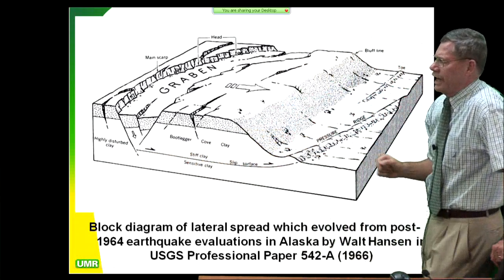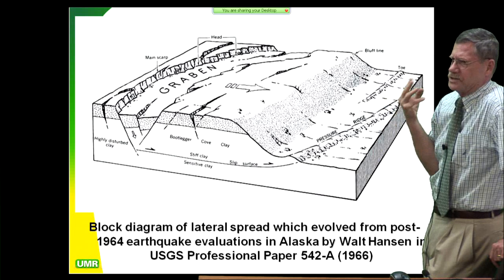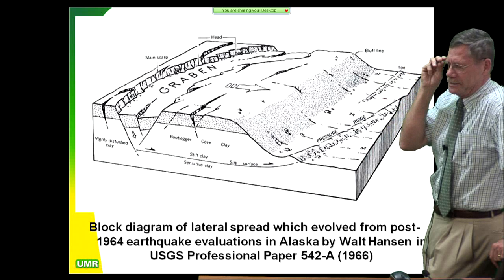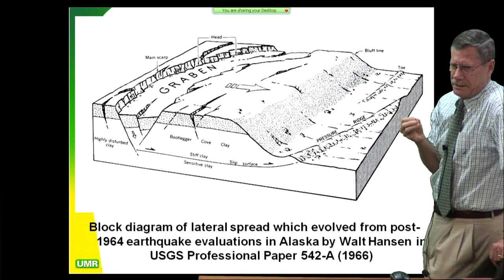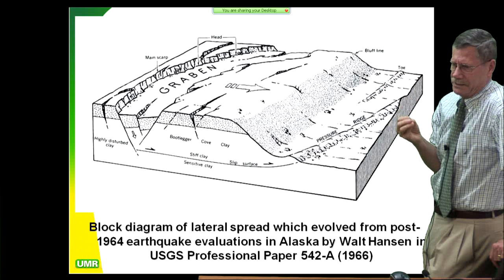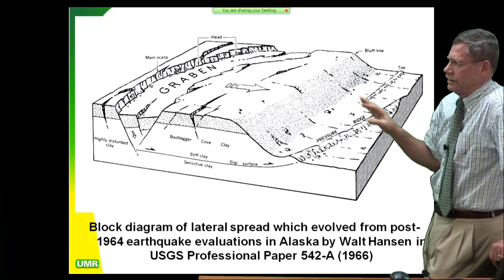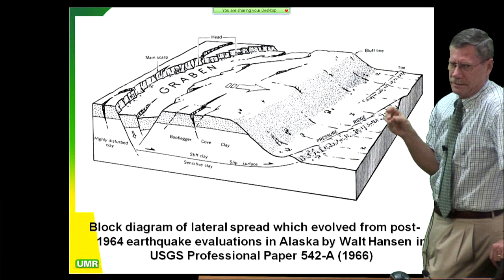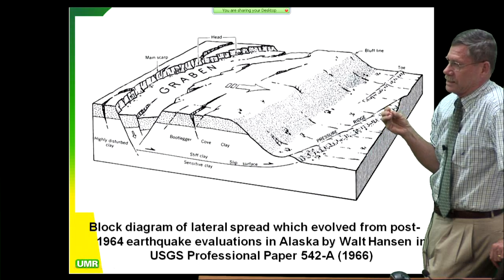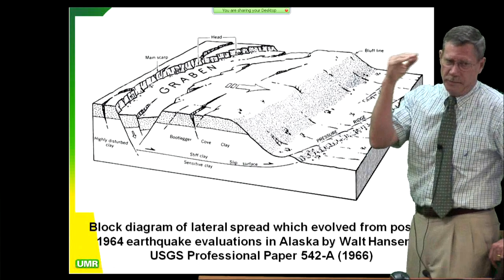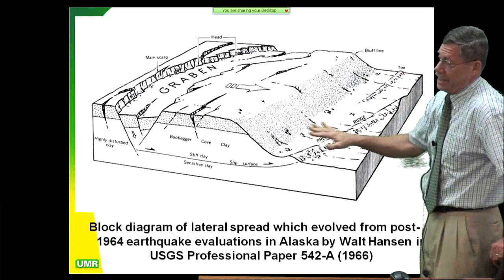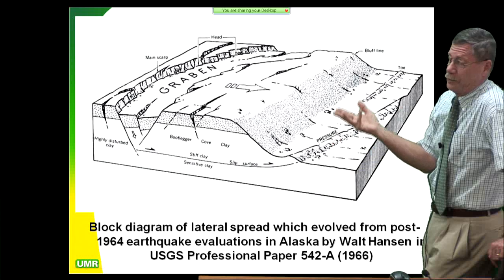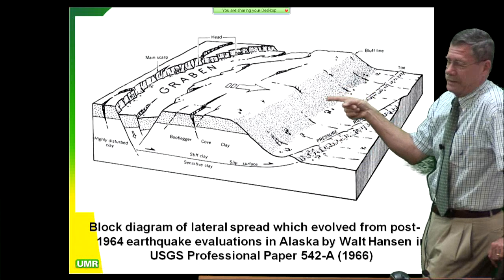The big problem you had in New Madrid and in Alaska was duration. You got to realize, we talk too much about magnitude. Peak ground accelerations don't increase once you get above about magnitude 6.4. What kills you in geotechnics is duration. Duration, duration, duration is what's important. So once you get above mag 6.4, your PGA value's going to probably peak out. You're going to start getting plastic deformation, and with each cycle of loading, you're just driving up the pore pressures, and you start getting stuff like this happening.